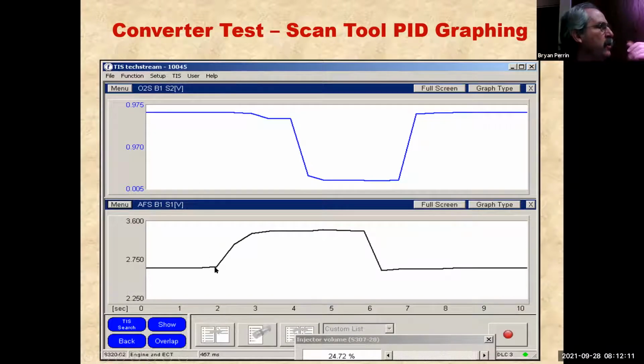So right here, I shifted it to lean. And right here is when I dropped. And this is gradual, not a great result because it wasn't abrupt, as well as this is actually seconds. So there's a couple factory scan tools that give you it in seconds, not frames. In this case, I've only got 2 seconds, 1, 2 of oxygen storage. That's Toyota's minimum. That's very concerning. Keep in mind, sometimes the tool can skew that.